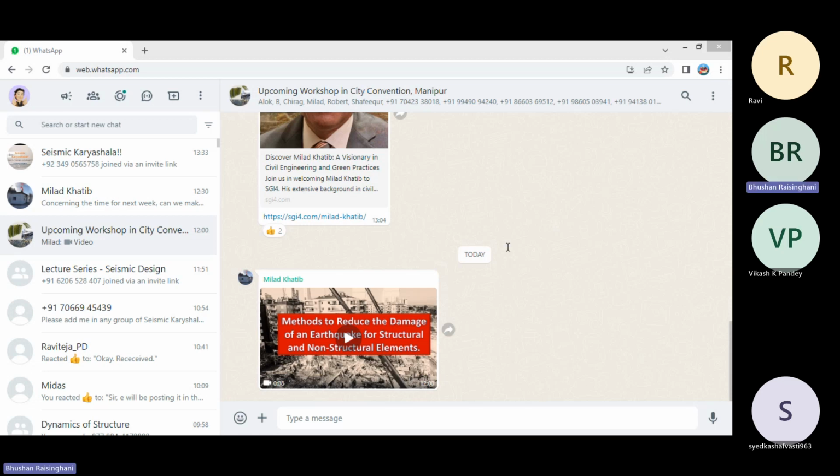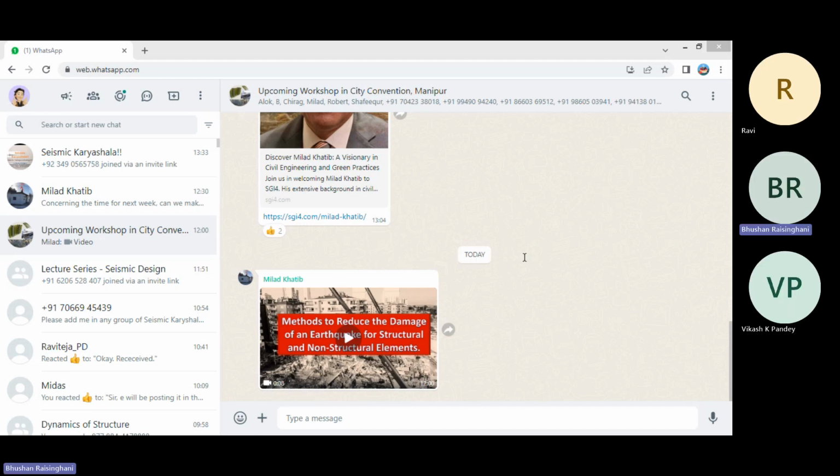So shear strength of a wall with openings should be checked at critical horizontal planes passing through openings. Additional steel reinforcement shall be provided along all four edges of opening in wall. So this is very simple. Only thing is, if there is an opening in the shear wall like this, how much area of steel that you have cut has to be provided in your two directions, 50% on both sides.